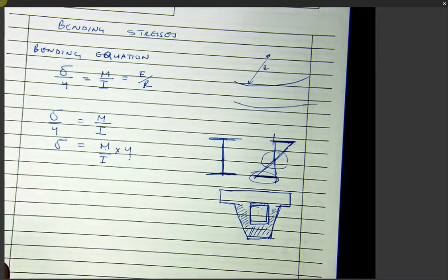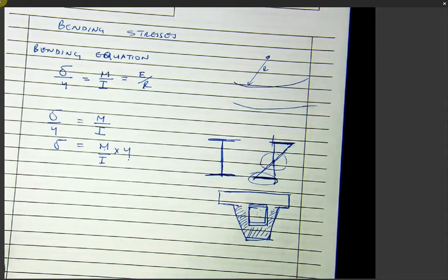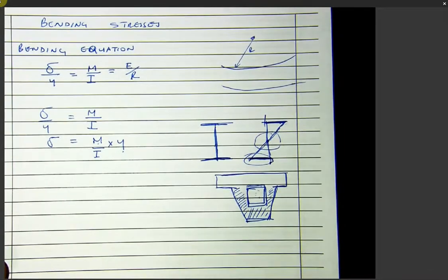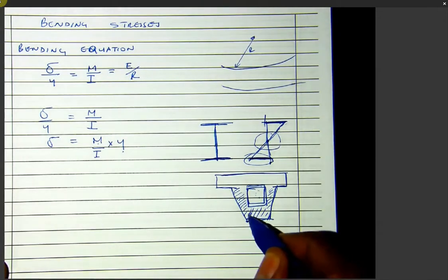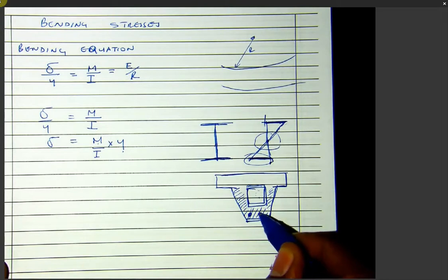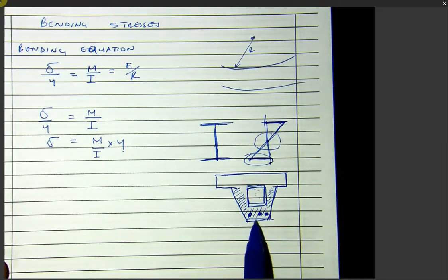There are limits as well that you must think about, that you don't want the stresses to be more than whatever, and the limits are determined by the reinforcement that you have there. You can't stress the bars more than what the bars can handle.